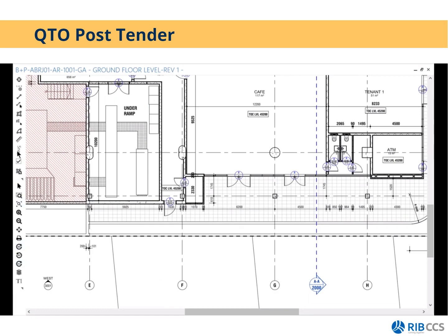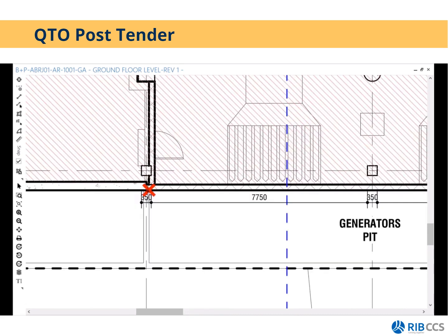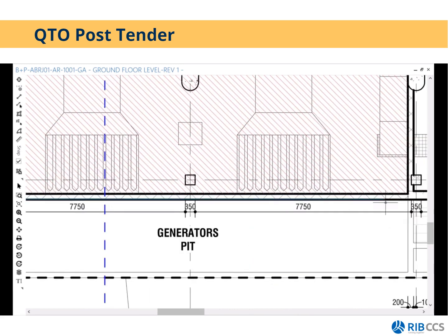Then I'm just going to detach my drawing to explain to you the drawing tools, because otherwise I can't see all of them. So the first drawing tool is the snapping tool. If I take my line tool and I click, for example, where this measurement on this wall would start, I have that little X. The system will automatically follow this line on the PDF. So even though my cursor is over there, my measurement is on that line.